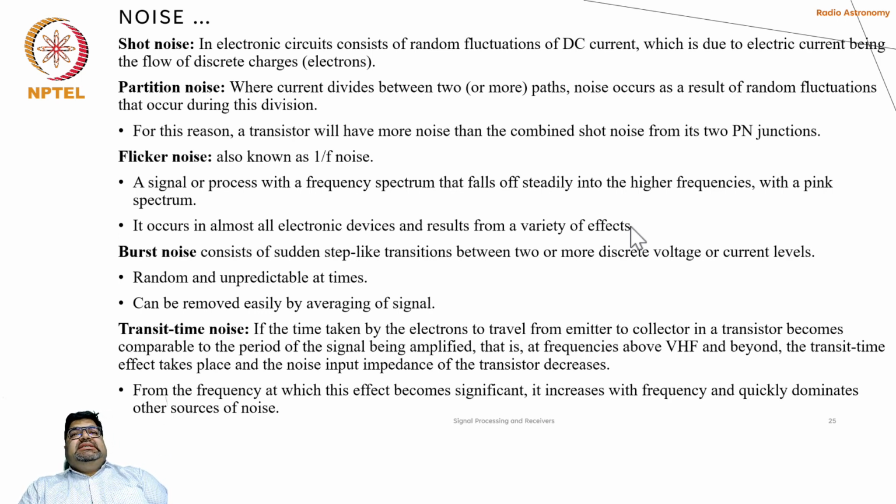Pink noise is a particular variety where the mu is not fixed. It varies with time. So there is no real mean for a long time if you track the signal for a long time. So that's one of the particular effects of flicker noise.